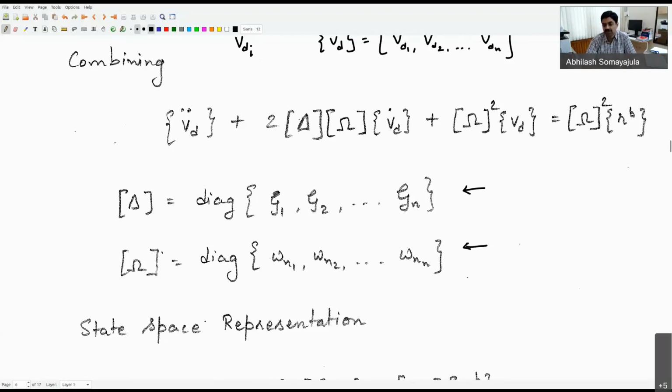It makes more intuitive sense when tuning that, okay, I want to add more damping into surge, or I want to add more damping into yaw. I can be directly adding the damping, rather than saying I'll add damping into yaw, but through surge. That is a little tricky, right? Not that it can't be done. It's not so easy or straightforward to grasp and understand when you're doing the tuning.